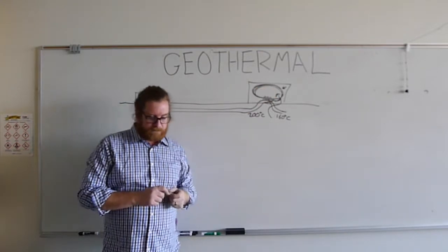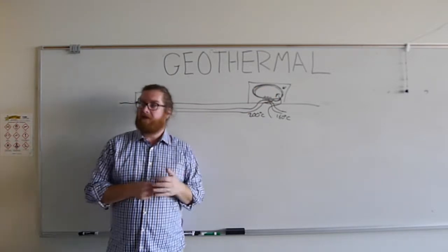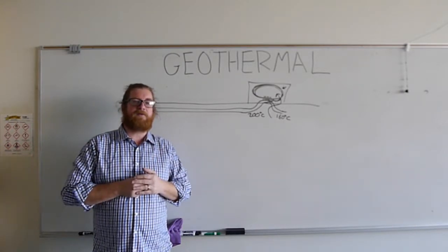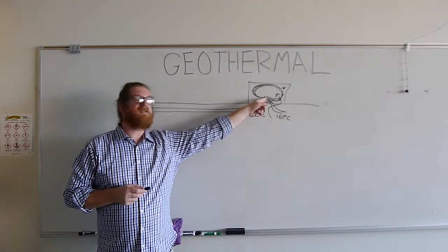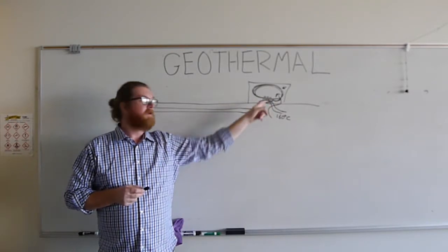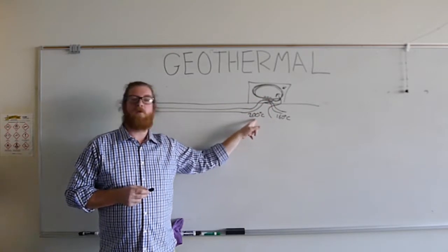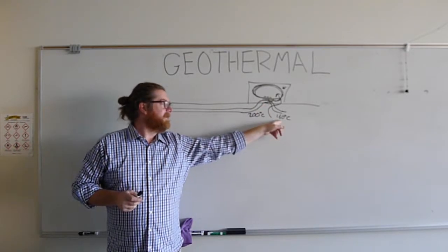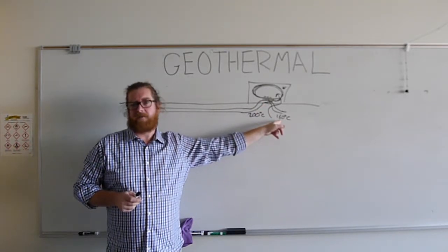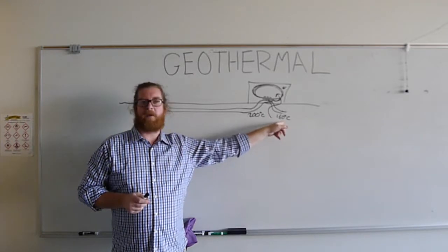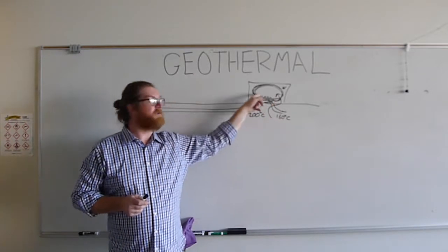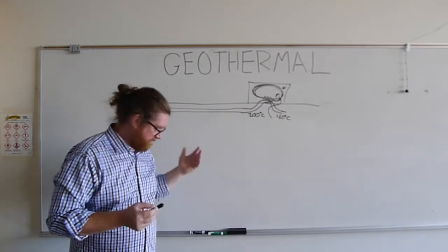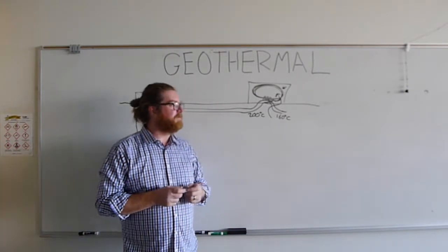And so one of the cool things is, I've talked to some of the folks over there, this really depends on how much money you spend on a heat exchanger. So some buildings will get the water at 200, and just using hypothetical numbers, it goes back at 180. They didn't take very much heat. But others will put the water back at like 120. They bought a really expensive heat exchanger. So it's kind of different, like I said, for all users.